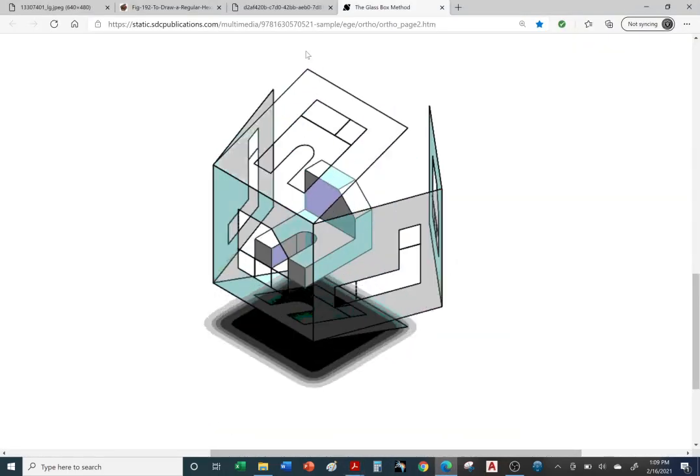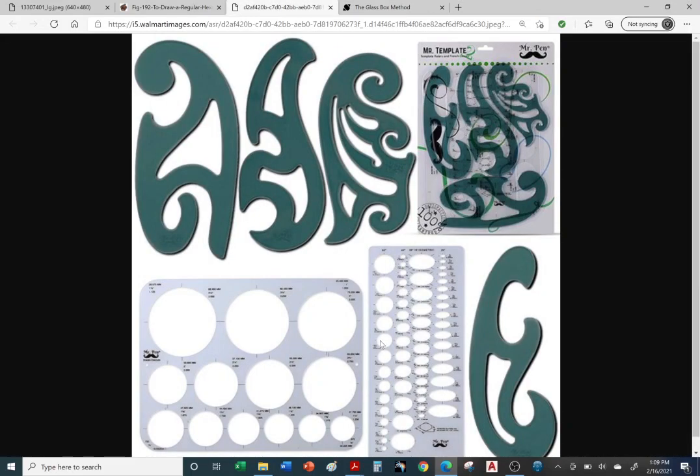If we go back to the templates, if you were making a drawing of this drawing template, for example, all you need is one view. Because if you look at it from the side, it's just a thin edge. So you would just draw one view and then call out the thickness of the material, whether it's 1/16 of an inch or 1/8 of an inch, for example. Something like this, one view is more than enough because it's a flat piece.